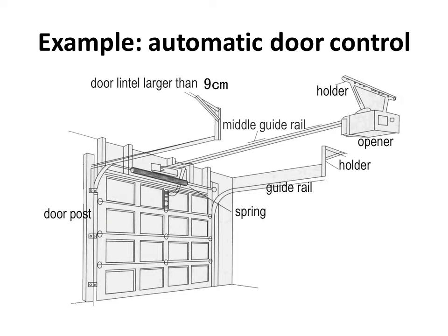An automatic garage door has a motor that can run forward or backward or upward or downward, and can have sensors in order to decide when to stop the upward run or the downward run. So in this case, we want to automate the task in which, if the control button is pressed for security for a couple seconds, the door will open until it reaches the upper limit, and it will stay there for about 1.5 minutes, and then drop back down until it's fully closed.